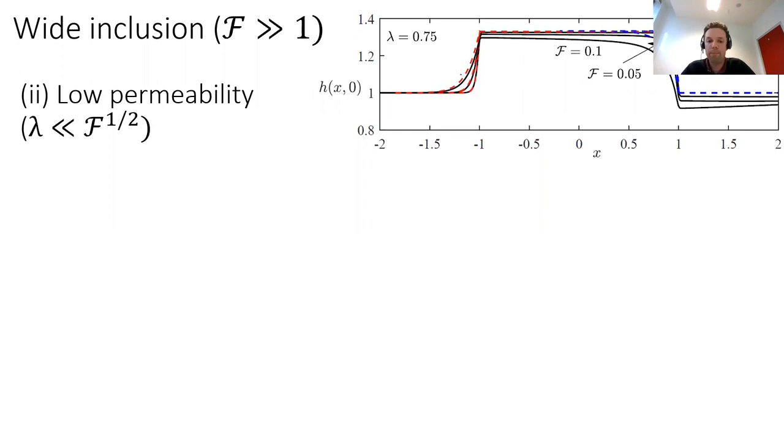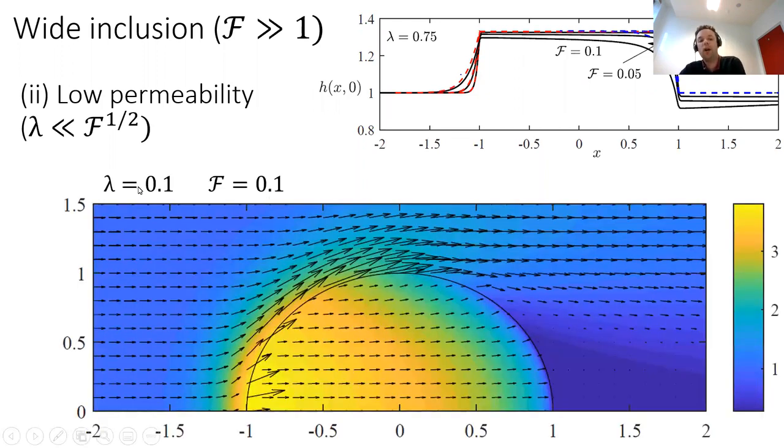And as that grows, as the permeability of the cylinder reduces, that can start to drive its own flow. And what happens, so this is for a 10 times less permeable cylinder, is that eventually that boundary layer drives the flow around in the tangential direction around the cylinder. And so there becomes more flow around the cylinder than there is flow into the cylinder. And we can use some simple flux balance arguments to try and understand what exactly is going on in this diversion regime.